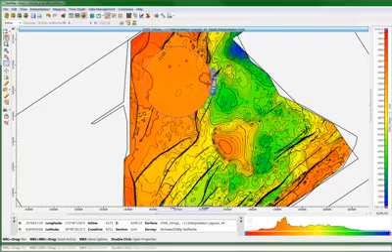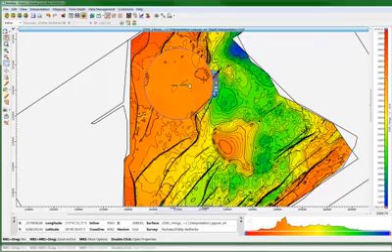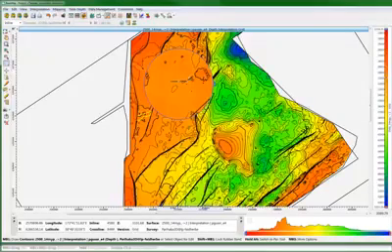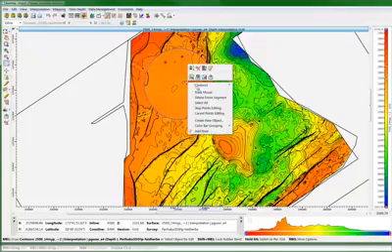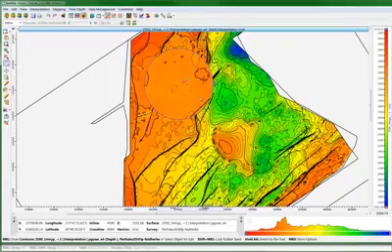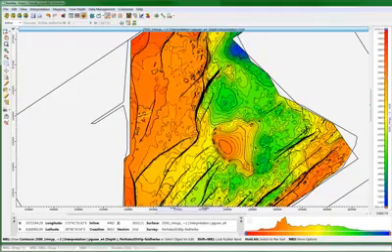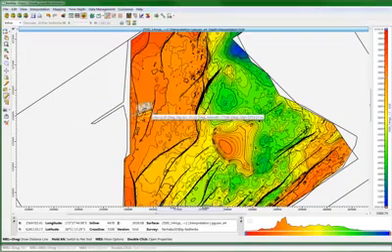By using the magnifier glass, we can zoom on a particular area while keeping a global view on our horizon. We can, for example, delete some patchy contours visible in the magnifier glass. We can see that the portion of channel cut by the two faults is materialized by a yellow polygon. We can use the ruler to measure its size in any direction.